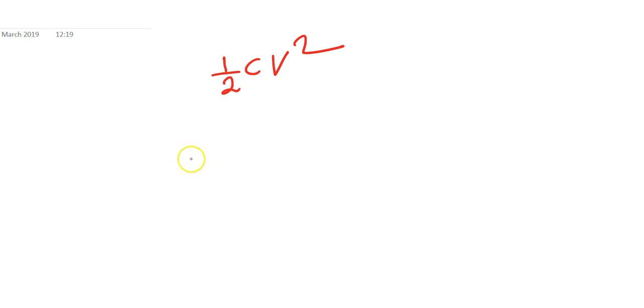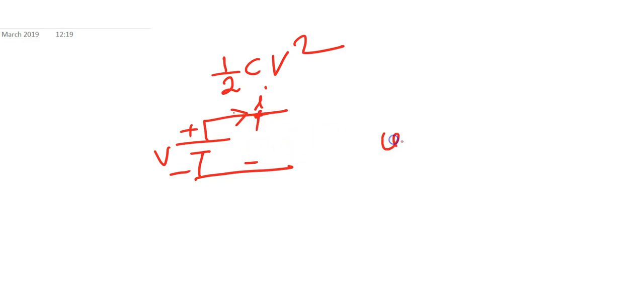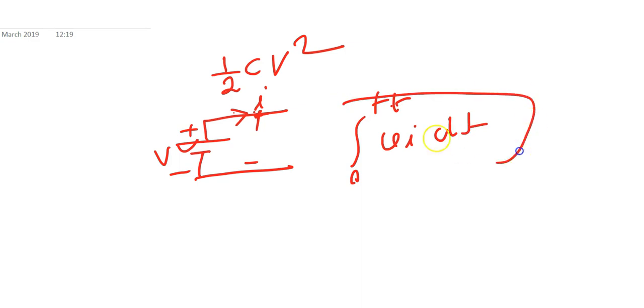Suppose this is a battery, with this voltage and current. How much energy is drawn from this? Same way, you use the relations. Find the voltage and the current, then integrate for that time dt. That much energy will be drawn from that battery. Always remember, resistors dissipate energy, and capacitors and inductors store energy.